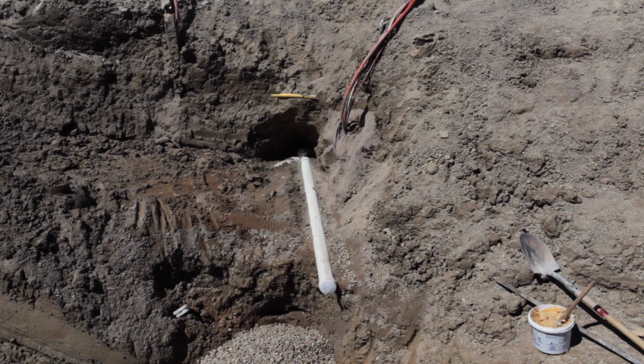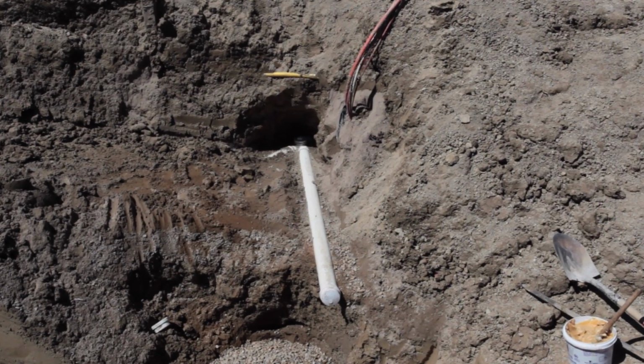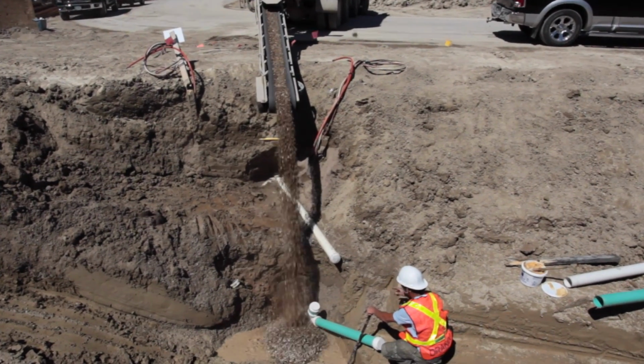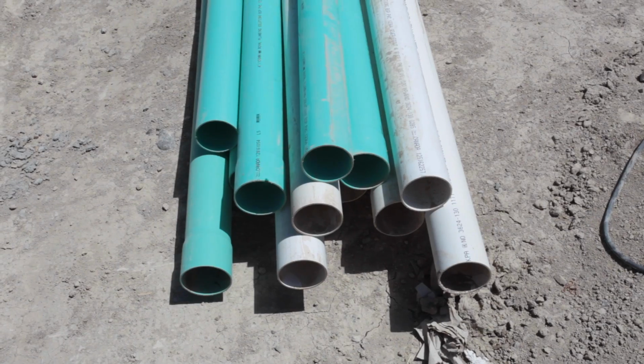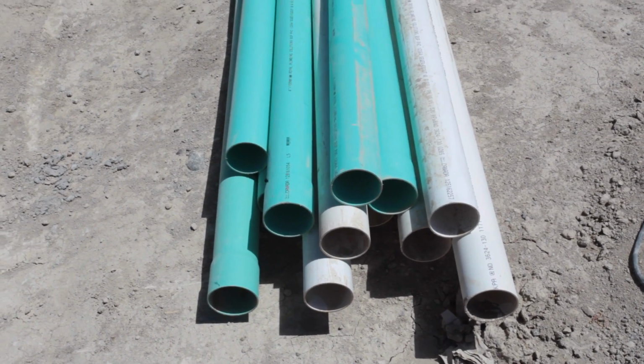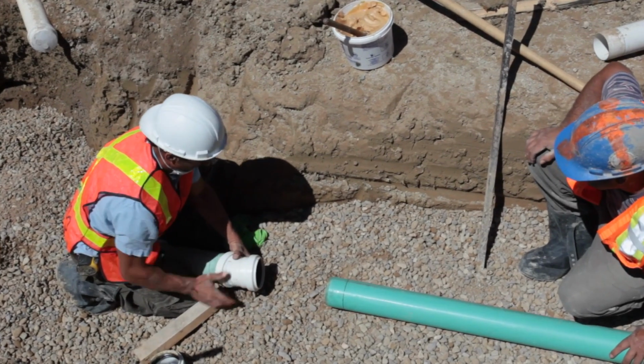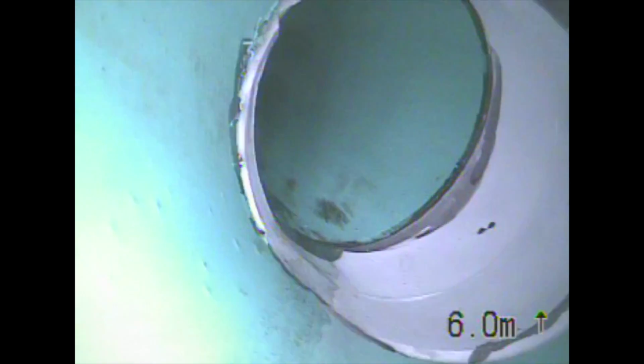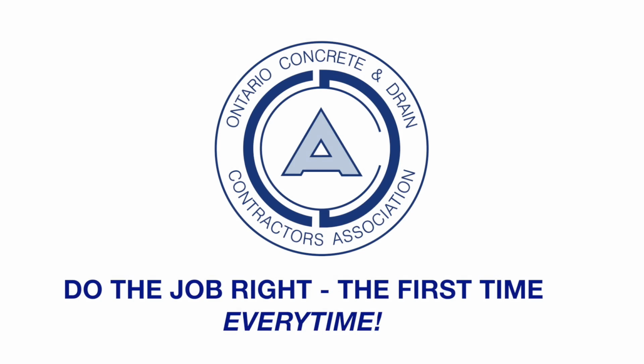We've looked at the OCDCA's recommended steps in: 1. Connection to existing sewer stubs. 2. Bedding, haunching, cover, and backfilling. 3. Installation of solvent weld pipe fittings. 4. Installation of gasket pipe and fittings. 5. Inspection, testing, and warranty. Following the Ontario Concrete and Drain Contractors Association industry best practices and the Ontario Building Code requirements, along with adhering to your company's safe work procedures, will ensure that you do the job right the first time, every time.